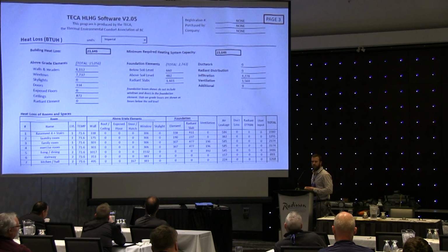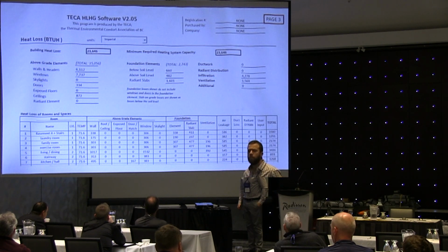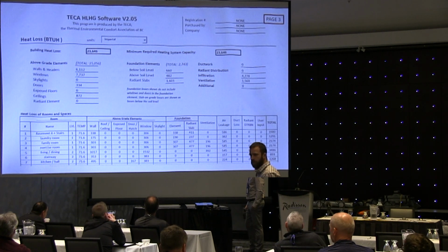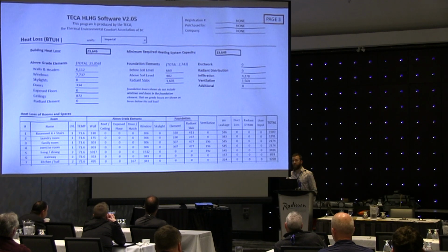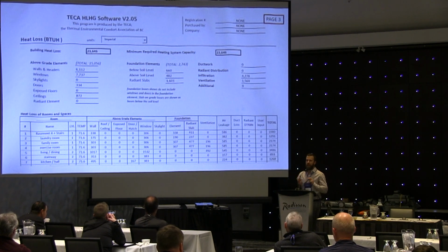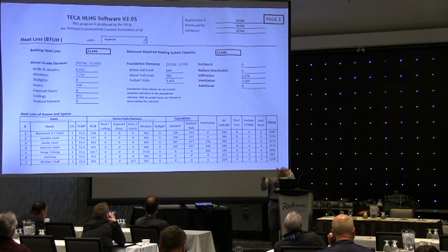Any questions? Just looking at that heating tool. So on the old ones, they have the zones broken out. So wall, exposed floor, window. Yeah, so heating and cooling zones is a step we don't take in this software. That would come in your heating system design phase. When you're doing the ductwork or the radiant layout, that's where you'd zone everything. Okay. So that would still be part of the package that gets handed in. Right. If you're also inspecting the ductwork, yes.